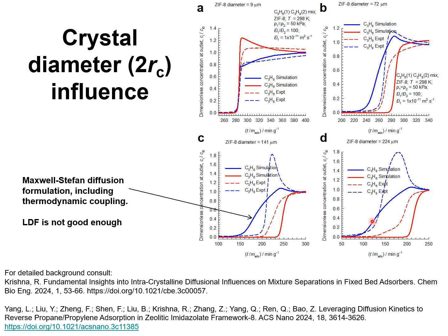And that is important in PSA separation schemes, because the achievement of high purity of propene that is recovered in the vacuum blowdown step is higher if propane is practically excluded from the pores. Therefore, increasing particle diameter is desirable.